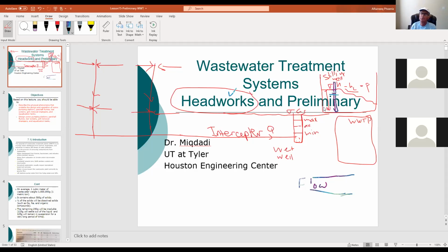Grease and oil are going to float on top, and they remove it. The tiny silt, clay, sand, and coffee grounds are forced to settle to the bottom of the grit removal unit, and they remove them from the bottom. Most grit removal units in modern days are aerated. They pump some kind of spiral air inside them. And you're going to design this as well.